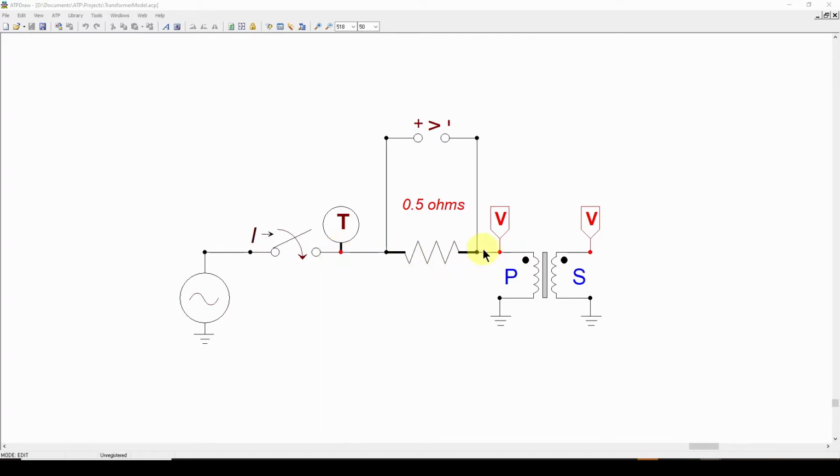And the only purpose of that is to give us a voltage so that when current is flowing into this winding, it flows through this resistor, and we can get some differential probes across this to measure on our scope the visual wave shape of this current flowing into the transformer to give us a better idea for what it looks like.